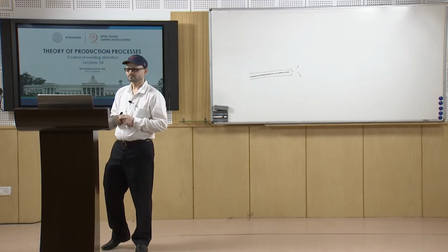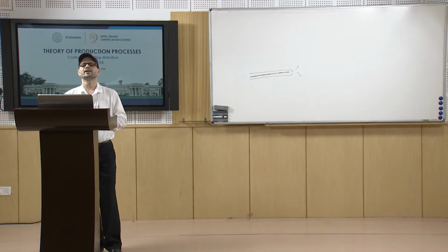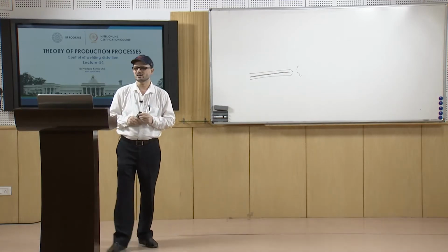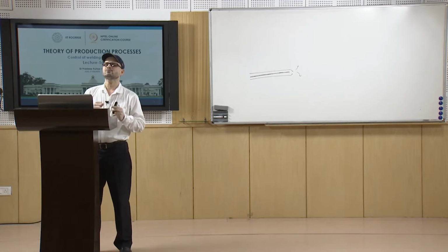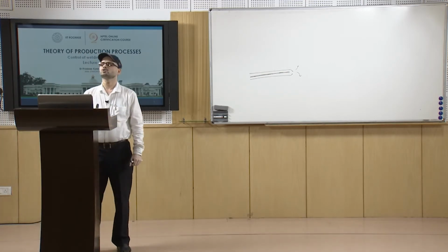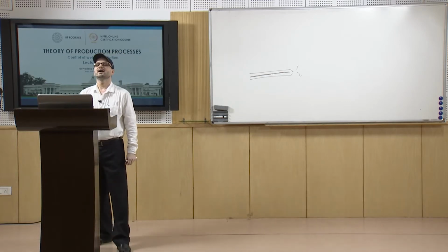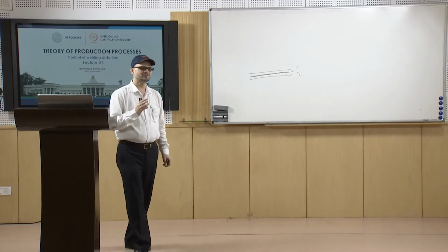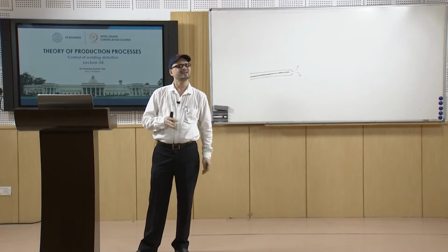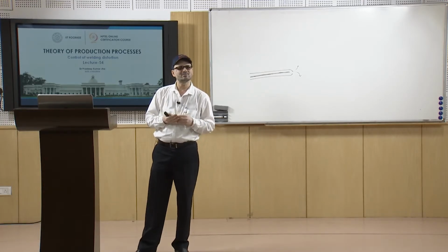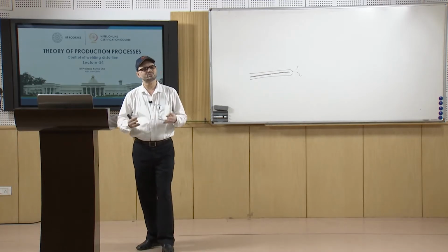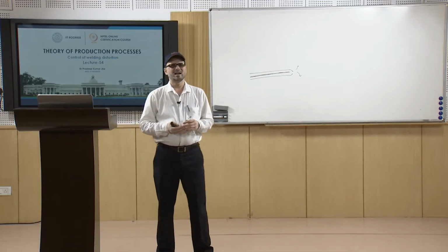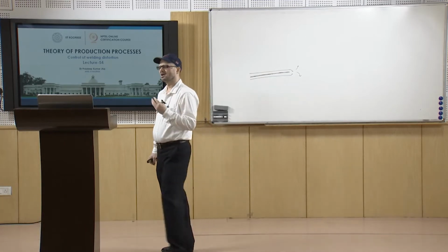Now, coming to the direction of welding. In what direction the welding should be carried out depends upon the welded structure. We have to take the precaution that it should be away from the point of restraint and towards the point of maximum freedom. Otherwise, if you move towards the point of restraint, there will be larger chances of distortion, because restraint reaction stresses are generated, and they will be larger and larger, so the chances of distortion will be larger.